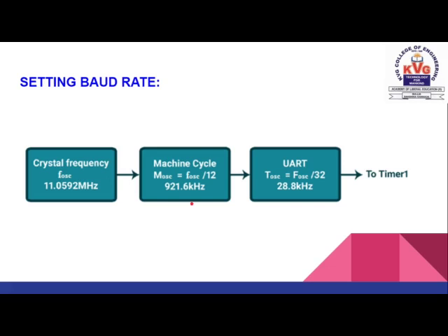The microcontroller is connected with the COM port of the PC for the purpose of serial communication. So, in order to allow data transfer between PC and microcontroller without any error, we must make sure that the baud rate of the microcontroller matches the baud rate of the PC's COM port. To meet the standard baud rates, generally, the crystal with